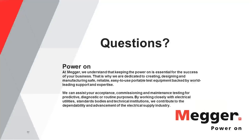What would be the minimum acceptable resistance for a wire with 600 volts insulation? Okay, as Jeff also mentioned, a go, no-go value will be something below 2 megaohms is something to investigate. Higher than that, you might let it go and accept it as a pass value.